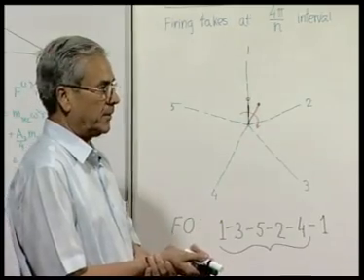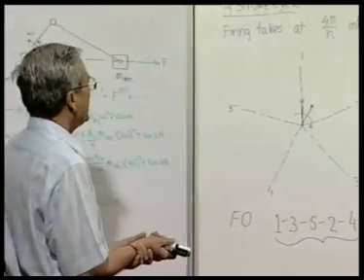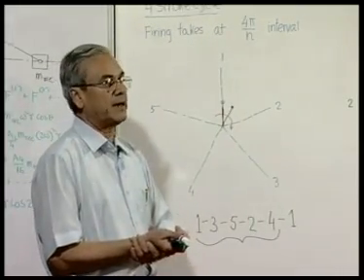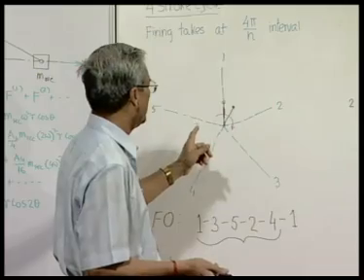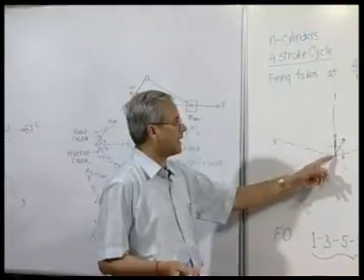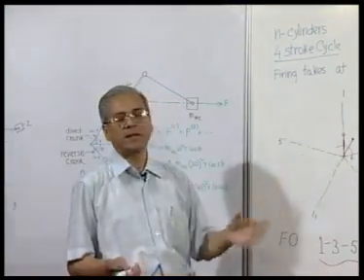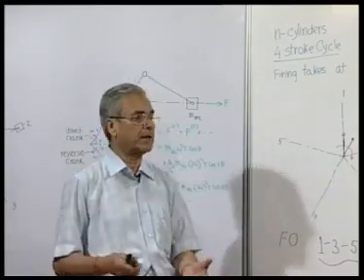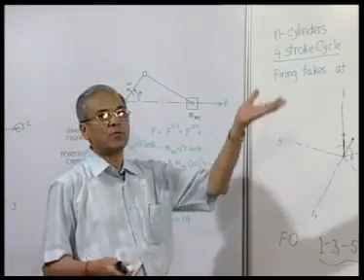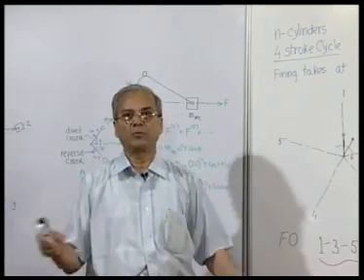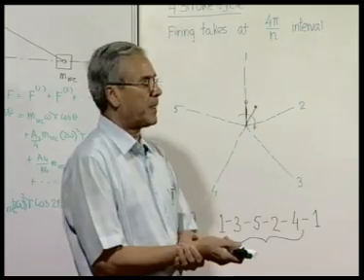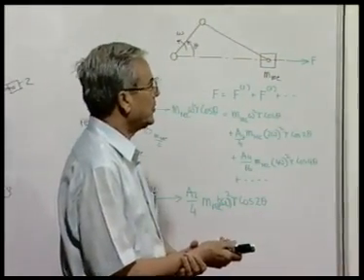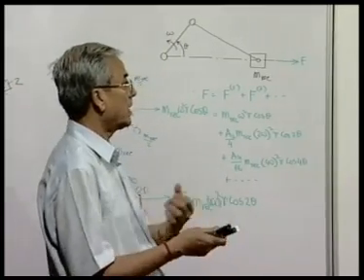It will be a nice exercise to really see at which level we first get the unbalanced force present. You will find that for an n cylinder engine, up to n minus 1 harmonics will be balanced, except of course the primary, because you remember the primary direct cranks are all aligned, and that centrifugal force can be easily balanced by a counterweight. After that, up to n minus 1 order unbalanced forces are all neutralized among themselves.